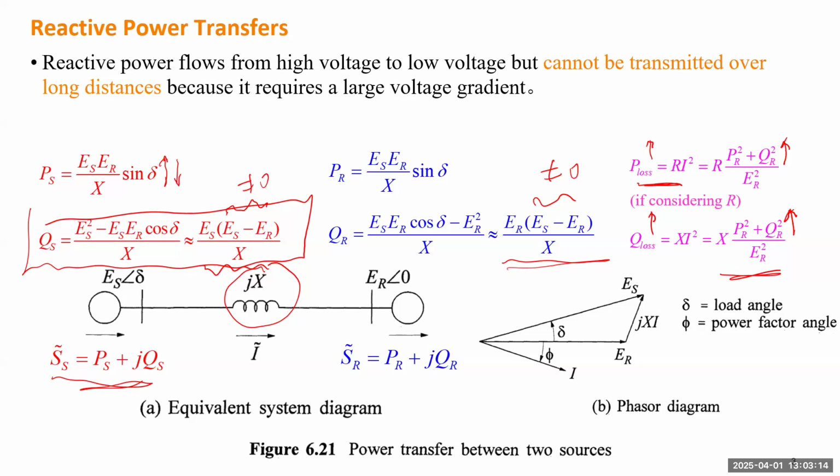But if that turns out to require ES much higher than ER, that's not reliable, because when you change all the voltages into per unit values, all the voltages can be different, but they will stay very close around one. For instance, for transmission systems, engineers usually expect a positive or negative 5% variation of voltage for a high voltage line.